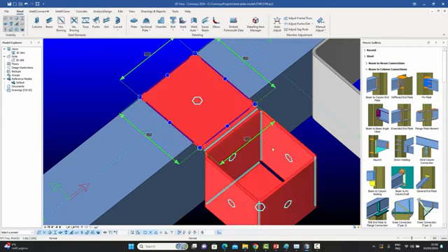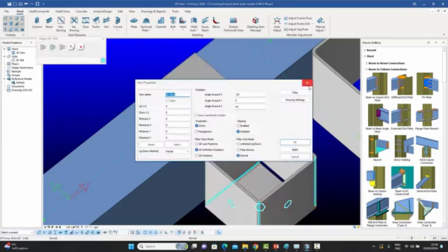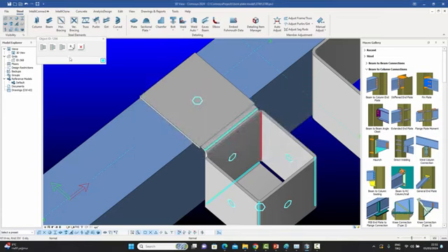The second handle are these lines which you see. These lines are the common edges where the plates were bent. And if you double click on these lines, then you have this new feature over here which allows you to bend according to the short edge. The two common edges might not be the same length, so you can connect the shorter edge, or you can connect the longer edge, or you can make a tapered sort of a connection.